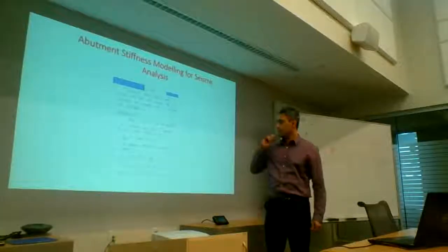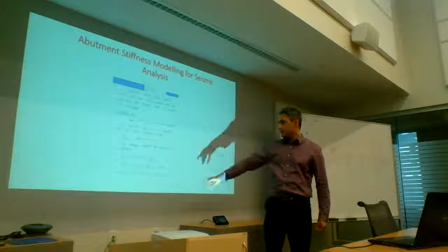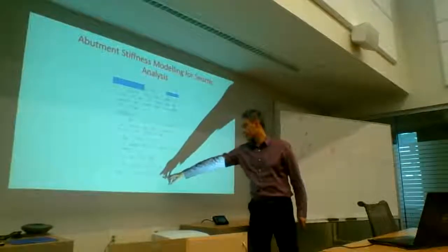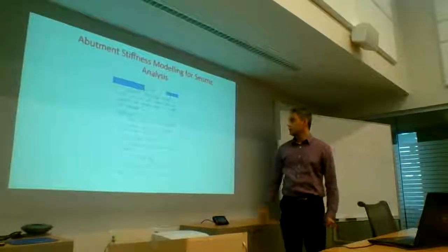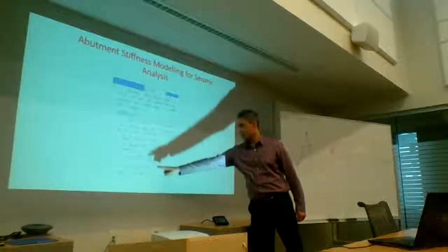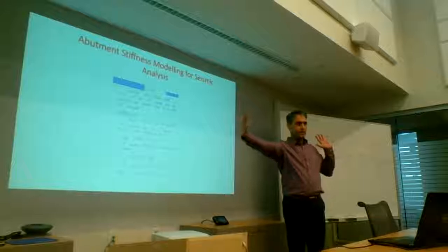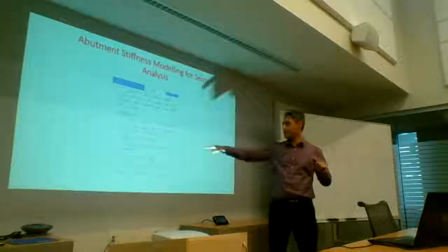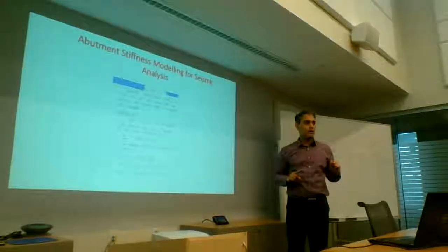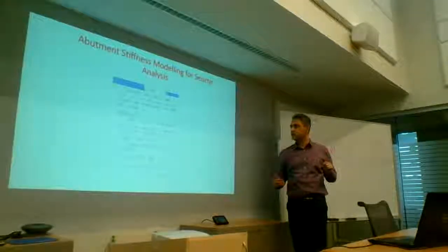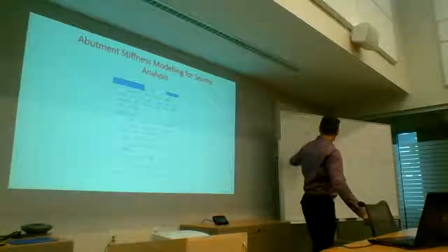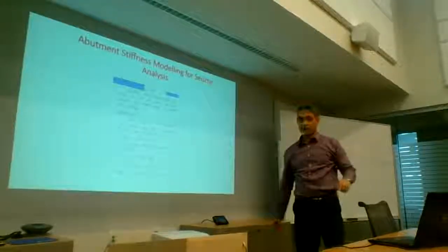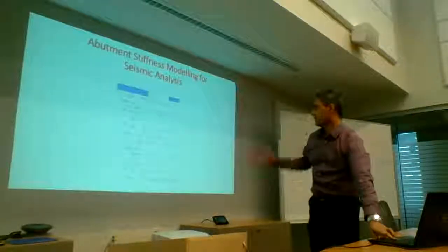So you can see here that the force in the diaphragm is 1,544. And so this is the capacity of what the diaphragm and the soil together can generate. The demand from the software is 6,100 kilonewtons. That's almost 4 times. So you've overshot this point by a factor of 4. You're sitting way up there. That means it's not correct. So now we go and we correct it.